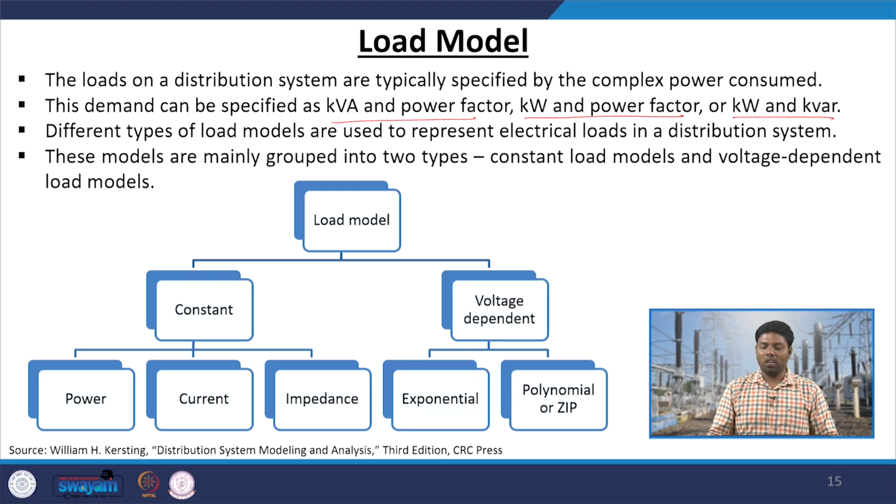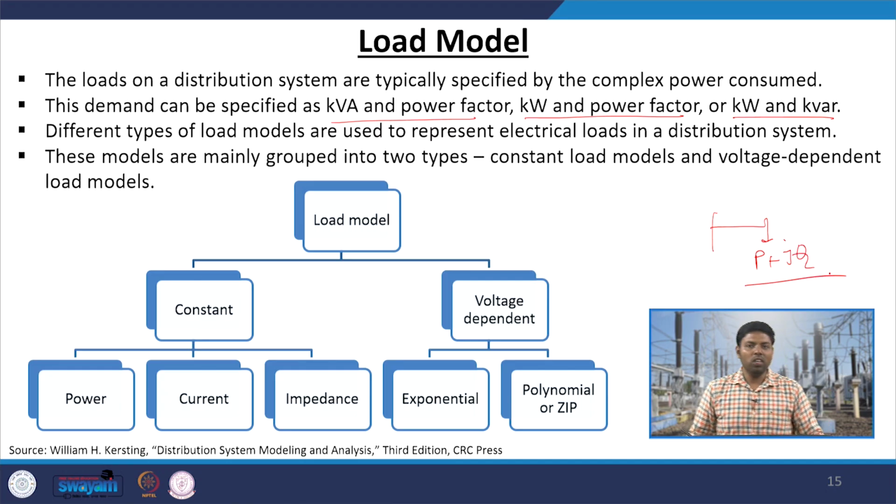As we know from the load flow solution, at each and every PQ bus we say how much load we want. Other than specifying these two separately, which we obviously can do, you can say how much apparent power your consumer is taking with a power factor value, or active power with a power factor value.